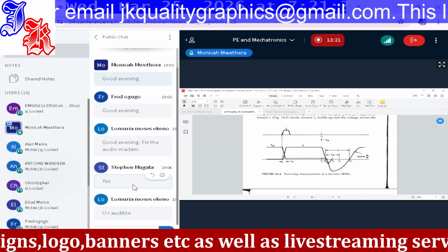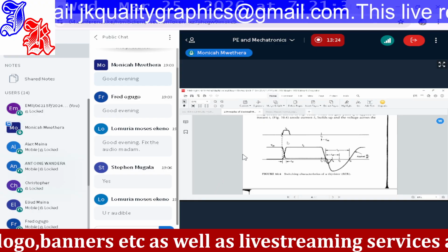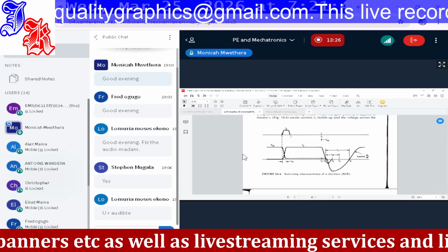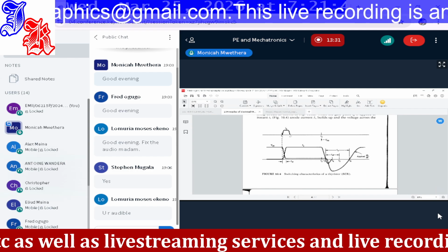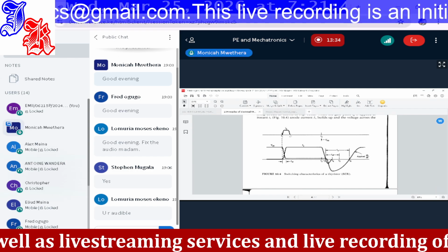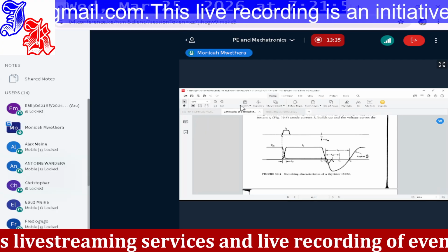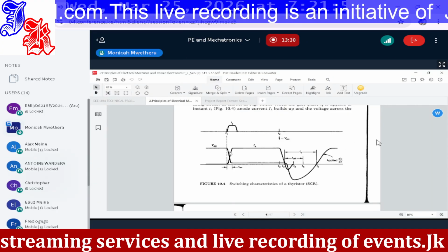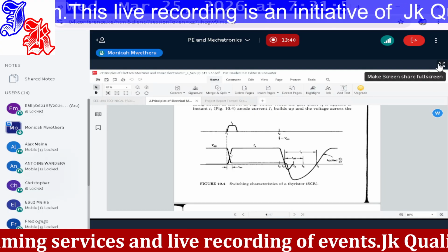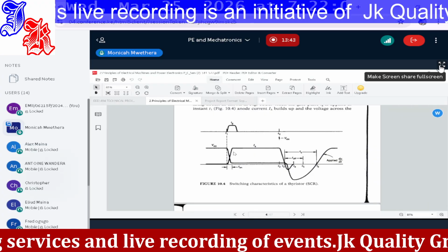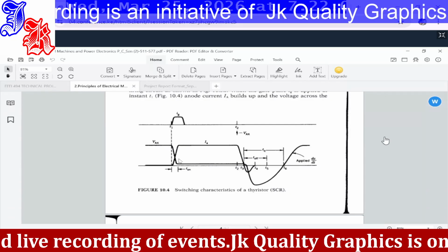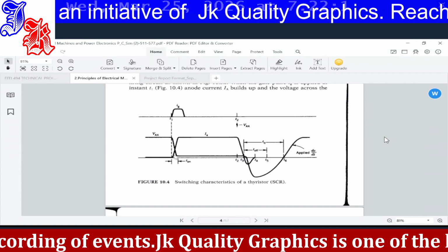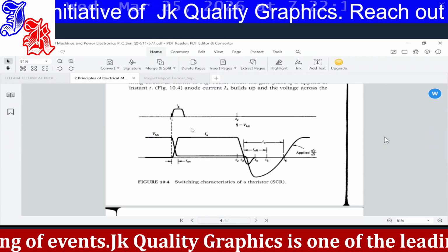We are saying initially, the way it is with the main supply only, we need to bring some current through the gate to ignite it. And so the moment we are injecting current or electrons within that region, we are able to reduce the depletion layer or the potential difference that was in that one reversed junction. So it reduces as the current builds. So it will reach a point where it will ignite fully. So it has started, and after that time, it switches on. So this is the switching on time, the time to switch on a thyristor using this IG current.